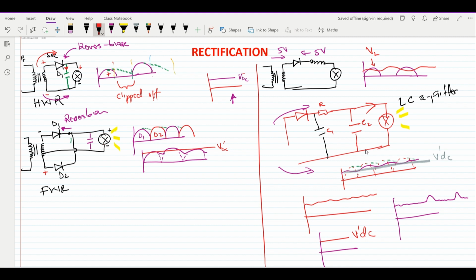After an inductor filter, we introduced a capacitor here that makes it an LC filter. After an LC filter, we introduced a second capacitor there. This makes it an LC pi filter. In an LC pi filter, the pi represents two capacitors. After an LC pi filter, we then did an RC pi filter, as you can see here.